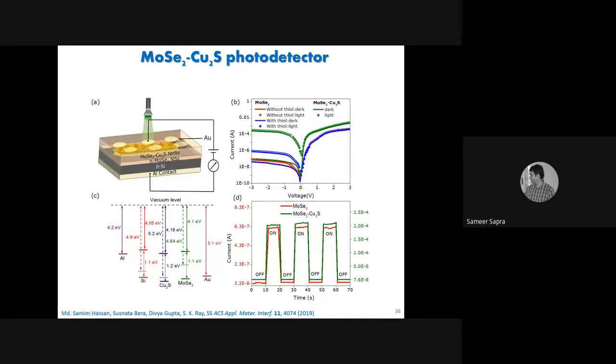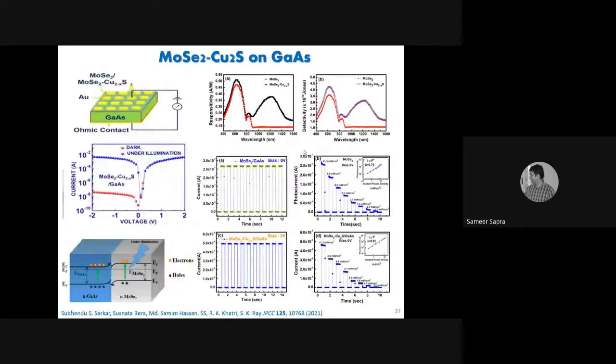And the good thing is with MoSe2 Cu2S, it's not actually Cu2S. Okay. It is actually Cu2-x S sulfide. Okay. It's actually 1.97 is what we've determined. And because of that, because of these copper vacancies, the holes that get created in the material show as plasmon resonances in the near infrared field. And these plasmon resonances also help in a photoresponsivity in the near infrared field.